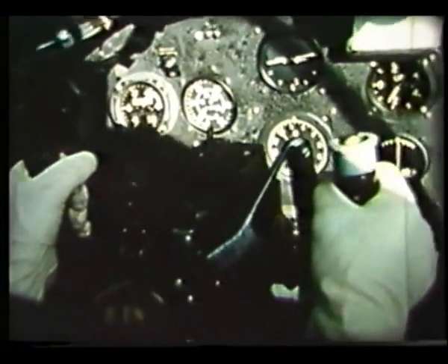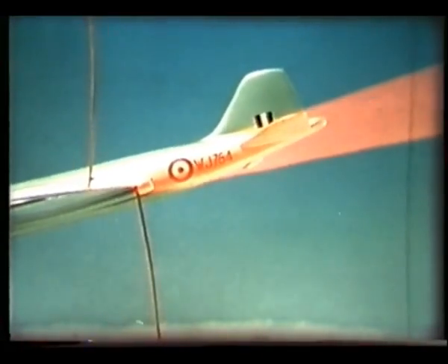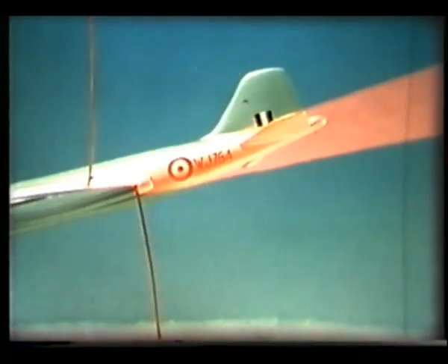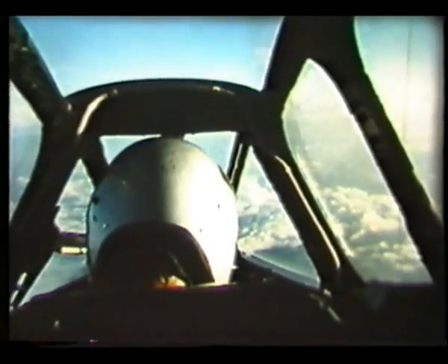There is also buffeting, caused by the turbulent separated airflow from the wing striking the tailplane. Or separation may affect other parts of the aircraft directly, such as the wing root junction or the cockpit canopy.